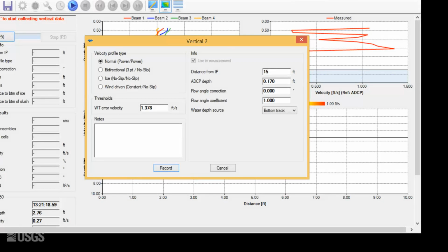After you measure this angle or coefficient, notice that you can enter an angle, like 8 degrees, or a coefficient, like 0.99. Either way, ensure you are measuring and noting these angles for every station, as there is no automated angle correction for open water measurements. You may find it useful to determine the azimuth of the cross-section to use as a tool for confirming your noted angles. A different video describes the process of accounting for angles in open water in more detail.